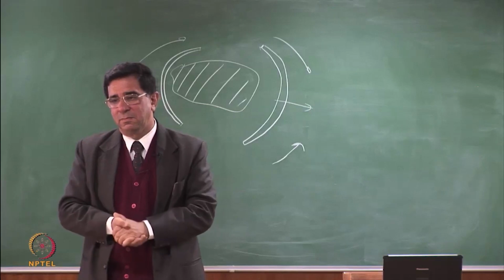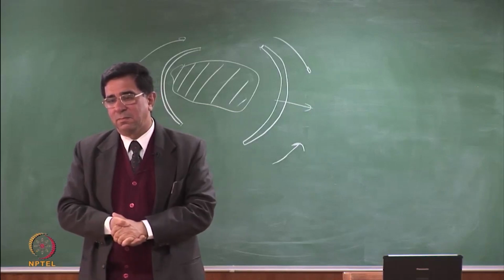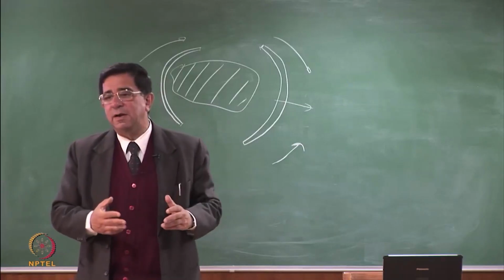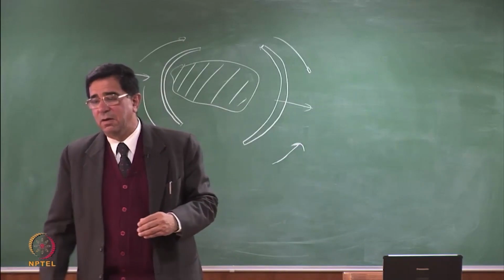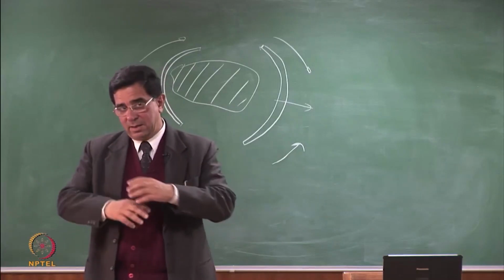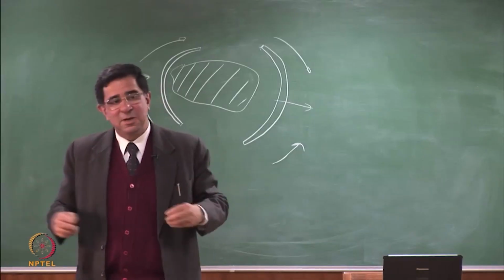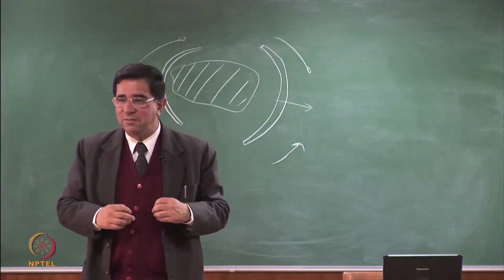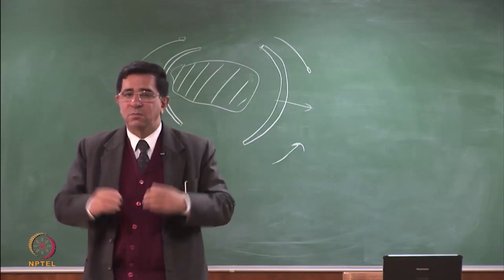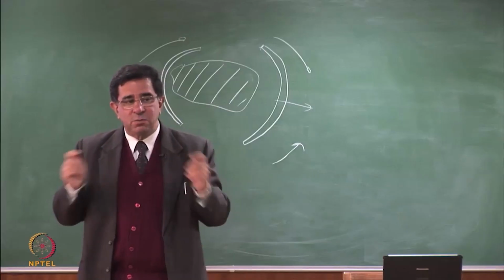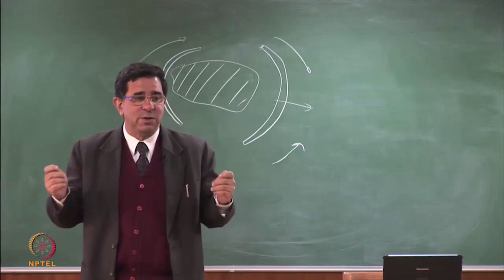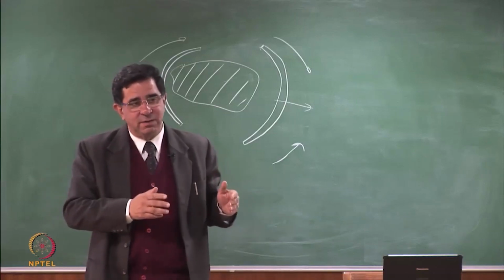So are these modules interconnected, or they have separate like leachate system and the gas connection? So the intent is to have interconnected, incrementally increasing landfill area. So they are interconnected, they are a part of a grand plan. If you don't make the phase plan correctly, you got it all wrong. So the question is, when do we put the cover? We don't put the cover after, if you have a landfill for 20 years, you don't put it after 20 years, you put it every year.